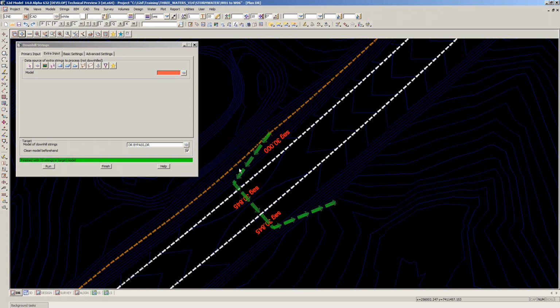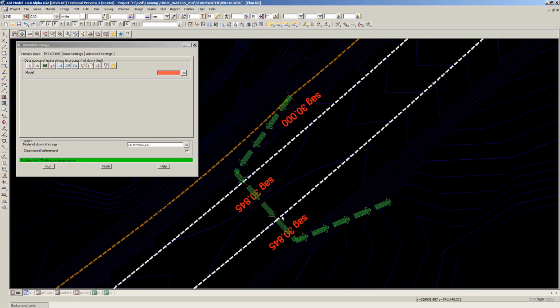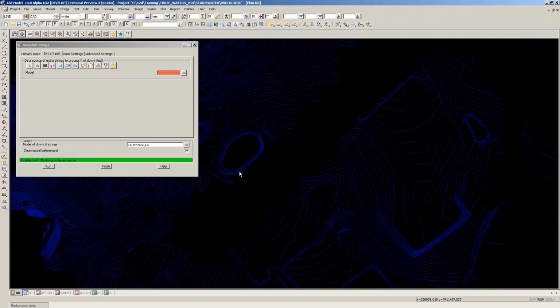But it actually serves double duty there. As it's drawn, it will convey any overtopping flow that doesn't make it into the culvert, but it also is going to cross the two nodes, or the drainage nodes that we haven't shown here, but they will interrelate, and potentially the two flows from the road drainage and the cross drainage systems could potentially mix there if this culvert ever overtops. So that's the purpose of that green string there. So what do we do with this?